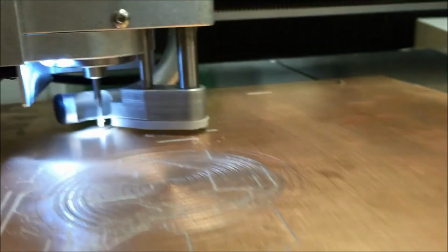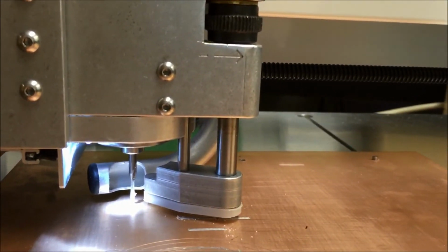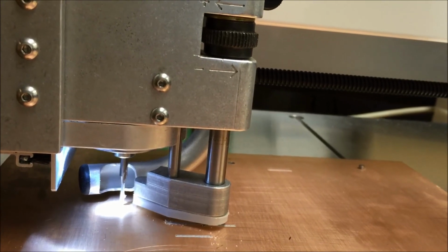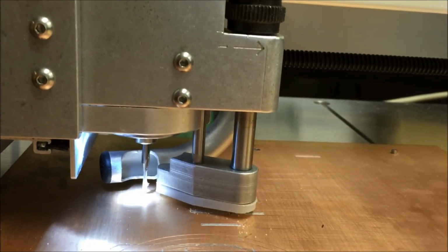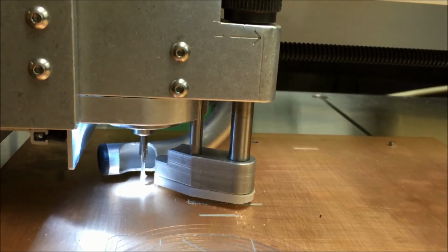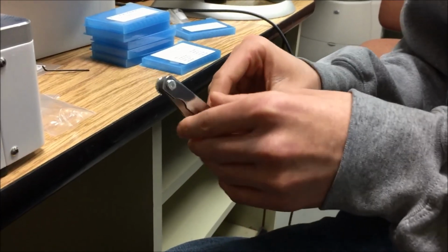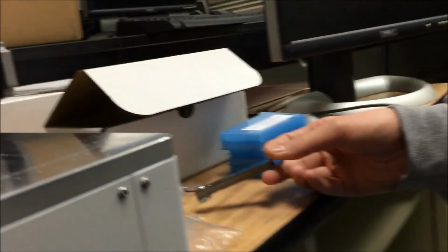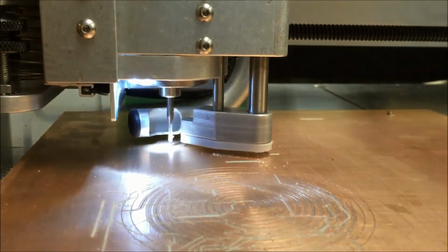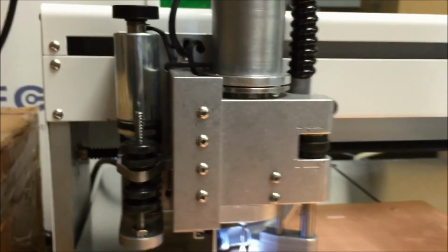Because you can imagine if it's got a lot of spacing, it's going to fly in until it actually hits it. So, are you saying that when you inserted the tool and tightened the set screw, there was some discretion you applied to how deep you inserted it? There's a little bit of discretion, but there's also some tools that you can use to do it. It comes with these feeler gauges. These are all a little bit too small, I would say, for actually setting it, but you could set it slightly higher than the biggest feeler gauge here, just so it's barely above the material.